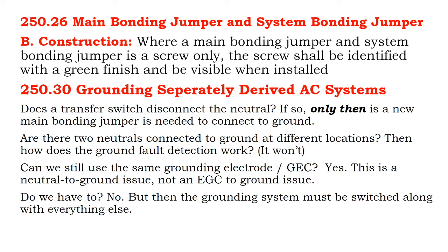I'd recommend just getting the larger 3-pole disconnect so that you don't screw yourself in the end. In fact, I would get fused 3-pole disconnect switches so that you can put an inline automatic transfer relay. Or really, if you just do a standard 3-pole disconnect switch with an inline automatic transfer relay, that would be how you get your automatic transfer plus your manual transfer.